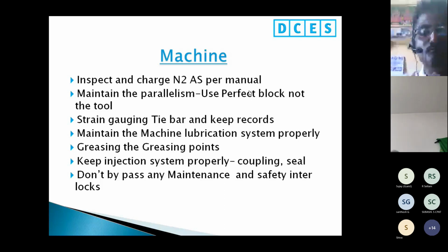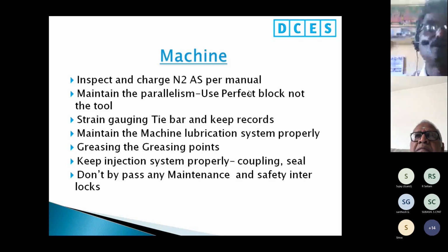block, not the tool. Sometimes in the automatic die casting machine, the people take the good die, they put it in between the two platen, they check the strain. It is not good practice. Must use the parallel blocks.